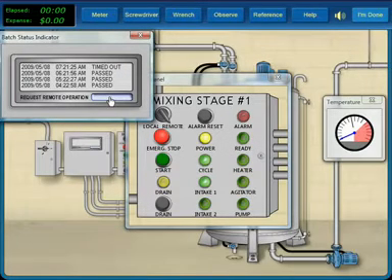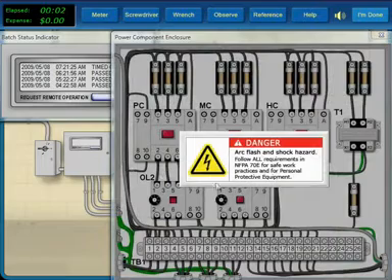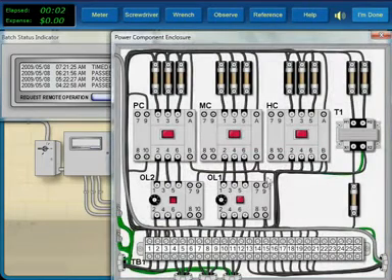When we restart the system, the cycle and intake 1 lights turn on and the tank begins to fill with the first fluid. At the midway point, intake 1 stops and intake 2 starts. Once the tank is full, the second intake stops. At this point, the agitator light should turn on, but it does not, and we do not hear the agitator start. Inside the power box, we see that the agitator's overload is tripped.